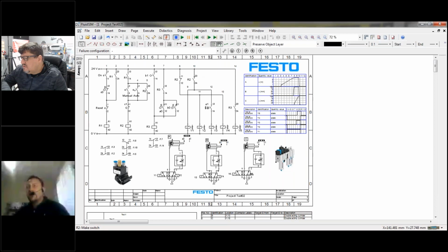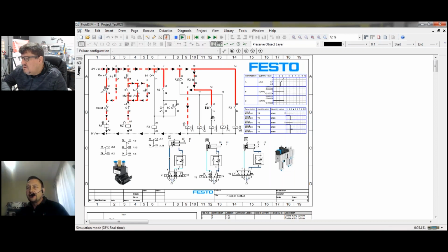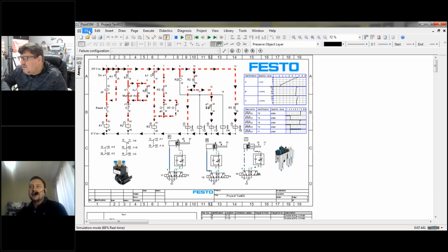And then you can also simulate. What's good about it is while it's in the drawing frame, when you simulate, you can actually pause it and send it to a client at a certain position. So the cylinder 1 moves forward, then cylinder 2 will start to move forward. And let's say, there we go, we stop it, we pause it, and now we export it as is.